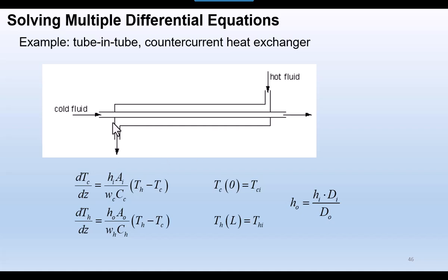But in order to solve the system moving forward in distance, we have to have an initial condition of the outlet temperature of the hot fluid, and that is something that at least for starters we have to estimate. Also, this heat transfer model is set up so that energy is conserved as it transfers from the hot fluid to the cold fluid. And what you will notice is that the